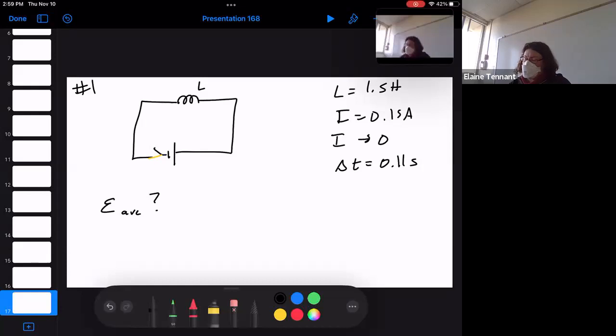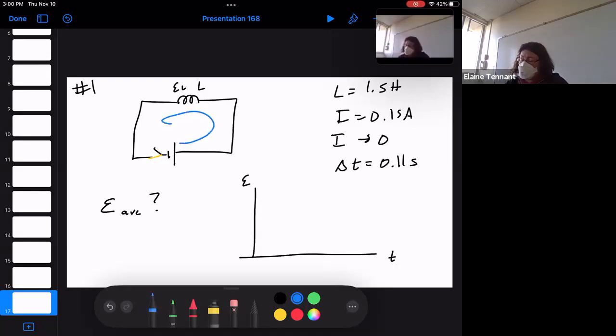Now let me ask you a question. If we graph this voltage with respect to time, and this is the voltage across that inductor. So we have the current going. It's been going for a really long time. So whatever the inductor wanted to block, it's done blocking it. Now it sees this current and wants to stay the same.